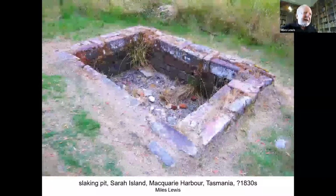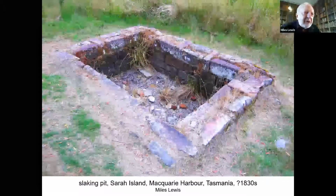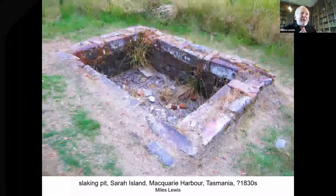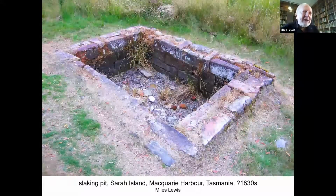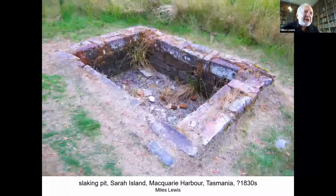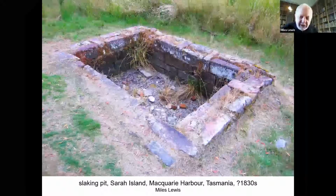This is a slaking pit. That's my interpretation of it. I'm pretty sure it's what it is, from the convict settlement of Macquarie Harbour in Tasmania. So this is where you put the burnt lime in, add the water, stir it up, and let it slake. Now, as I said, it's a dangerous process. There's a lot of heat and spitting, so it's worth having a masonry pit to do it in.